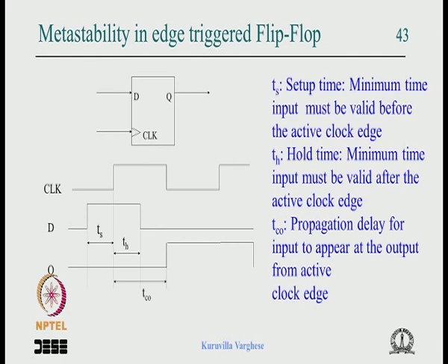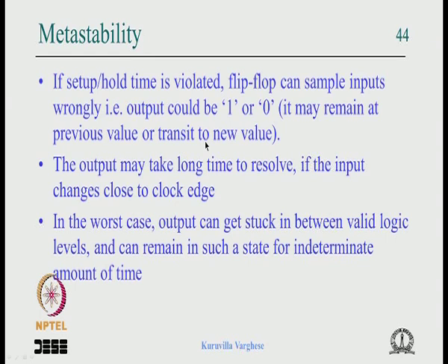So that is the basic issue, what is called metastability. In an edge triggered flip flop, if the setup or hold time is not met, we are not sure of the output, it can take longer to resolve, it can get stuck in between, which is the worst kind of thing. So that is what I have summarized here.